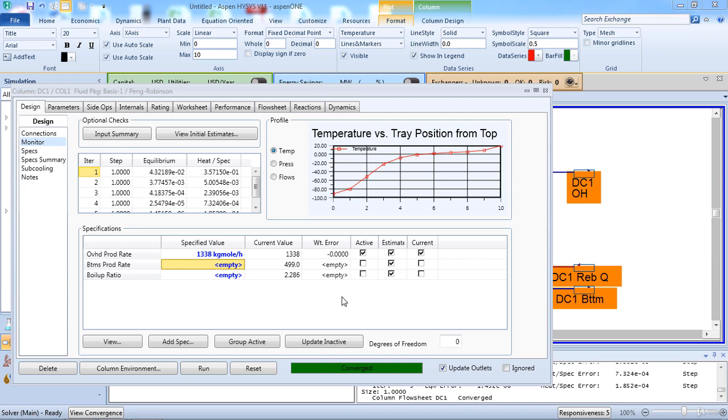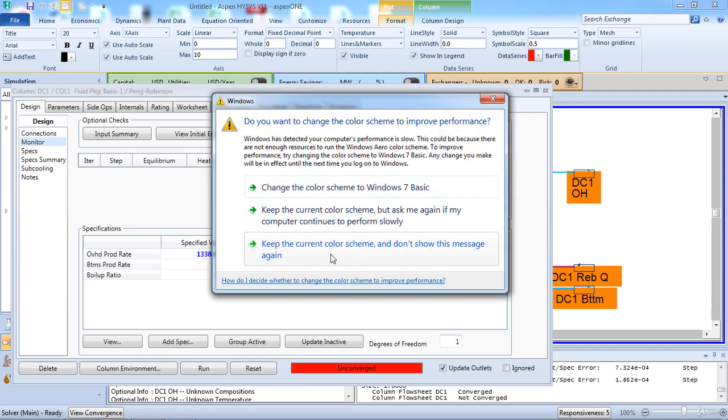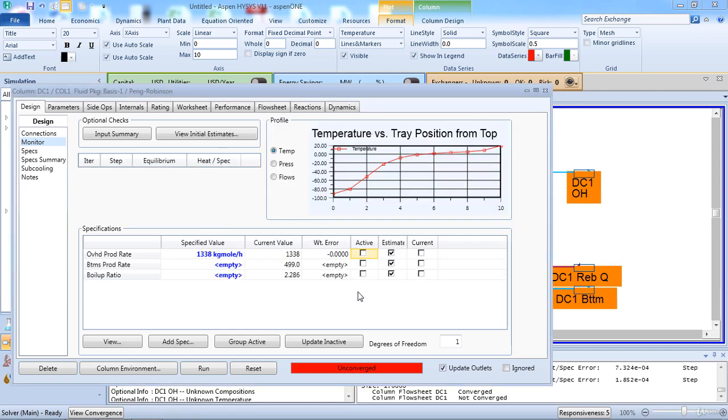However, it doesn't make sense to make the outlet overhead flow rate that we defined here constant, because the function of the demethanizer is to give outputs with the specifications that I require, which is the composition, not constant rate. Any changes in the feed will result in non-desirable specifications at the outlet, because you have determined the outlet flow rate and not the outlet specifications. So now I have to change that, and I will ask HYSYS to fix the overhead outlet composition, not the flow rate. So I will deactivate this, and I want the outlet methane to be 96%, regardless of the flow rate.